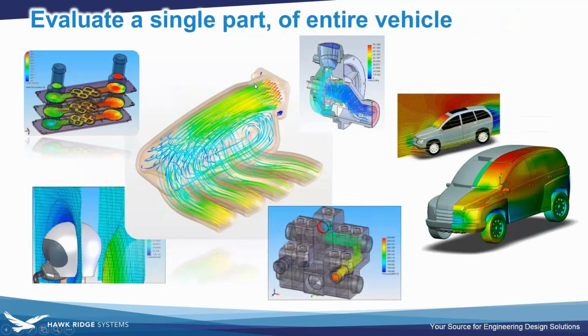Of course, what we really looked at here is a small set of what you may want to do with flow simulation. You could examine not just internal engine components like what we looked at, but for example, flow in an intake manifold itself and the header of the exhaust. Maybe you'd want to do a simulation of the heat exchanger like a turbo intercooler to figure out if you can lower air temperature more effectively before going into forced convection. You could look at aerodynamics of the vehicle itself, whether that means just pressure plots on the surface of the vehicle or streamlines as it goes around.